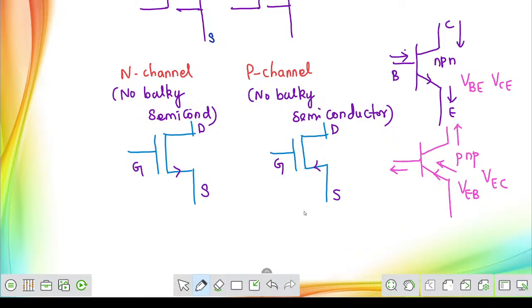Everything is opposite. So the conclusion is, in NPN transistor we have a back-to-back diode connection represented internally like this. In case of PNP transistor, it is the reverse. The diode will be like this, since the diode directions are opposite to each other. The representation is completely different; PNP and NPN are opposite even structure wise. Same thing with the MOSFET: here also we have three terminals, gate, source, drain, and again gate, drain, source.